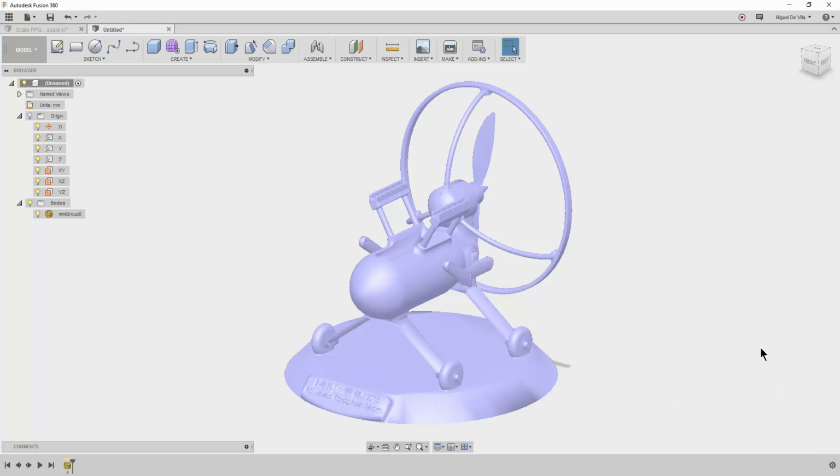The reason I chose this file in particular is this is the paraglider. I exported it out from SolidWorks a couple of summers ago when I was working on it as a summer project, and it actually has quite a few imperfections. Now, if you run this through a slicer, it'll look just fine. It'll process out very cleanly. That's because slicers can approximate out any errors within a mesh, like little floating closed mesh particles, intersections, holes, and all other problems that make it difficult for Fusion 360 to process effectively.